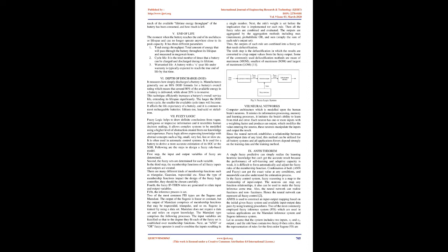4. State of health, SOH. A measurement that reflects the general condition of a battery and its ability to deliver the specified performance compared with a fresh battery. It depends on factors such as charge acceptance, internal resistance, voltage, and self-discharge. It is a measure of the long-term capability of the battery and gives an indication, not an absolute measurement, of how much of the available lifetime energy throughput of the battery has been consumed, and how much is left.